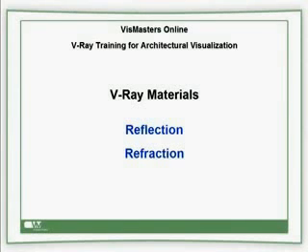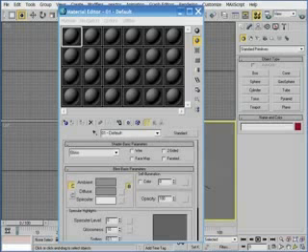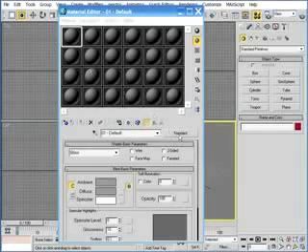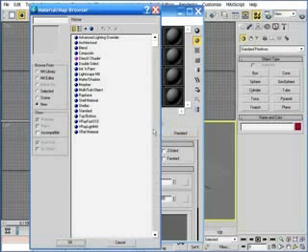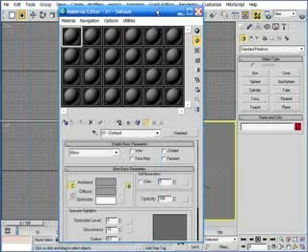Okay, so when you open the material editor, you should see nothing different unless you have adjusted your default Max startup interface to show VRay materials by default. And if you haven't enabled VRay as your render engine through the Assign Renderer rollout in the Render Scene dialog box, you're not going to see all the VRay material types available, just these here, which won't do you any good by themselves. As a side note, when VRay is not the selected renderer, you will see a simple black sample slot object rather than the correct object appearance.